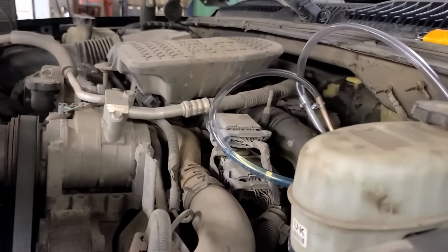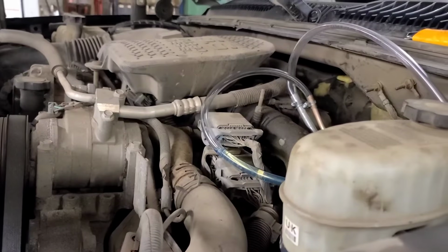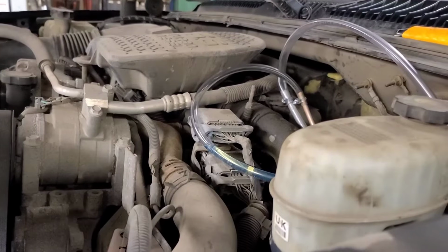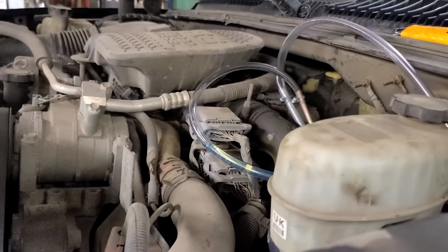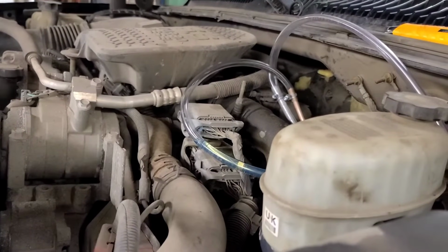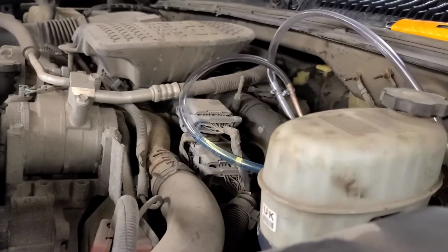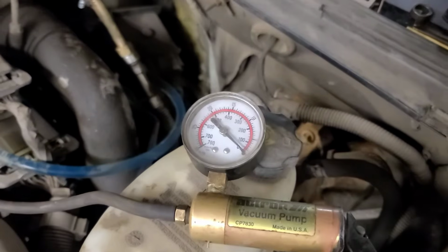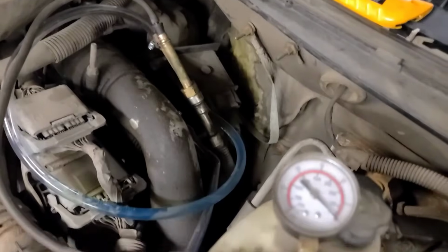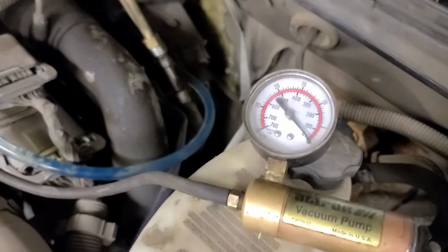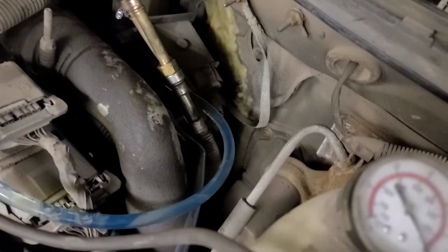Of course, smoke testing the line is not conclusive because it's very, very low pressure, and this line is actually under a vacuum. So I'm thinking of running a new line or capping the line at one end and pressure testing it, see if I can see a specific leak now that there's fuel in the line. So I capped the line at the tank, or at the connection going to the short pipe at the tank. So it should be sealed, and if I put a vacuum pump on the line, as you can see, it doesn't hold vacuum. Yet I can't see a leak anywhere.